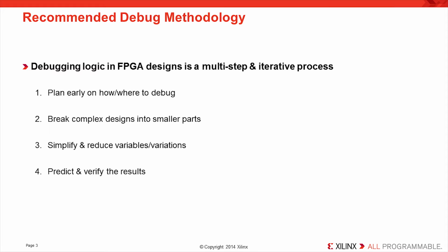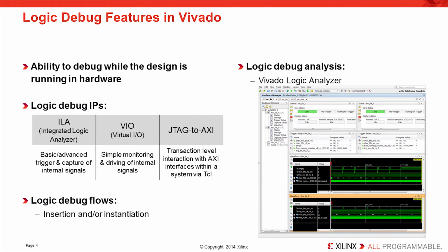results. Vivado provides various debug IP and tool features that enable you to easily debug your design while it is running in hardware. This is effective because you debug your timing accurate and post-implemented design in the actual system environment and speeds. Multiple debug IPs can be used to debug the logic in your design.